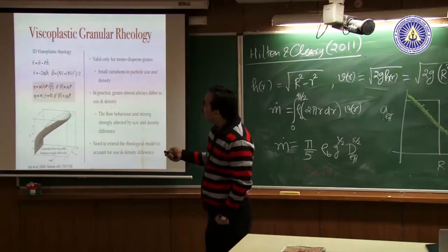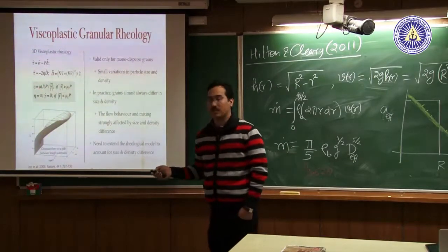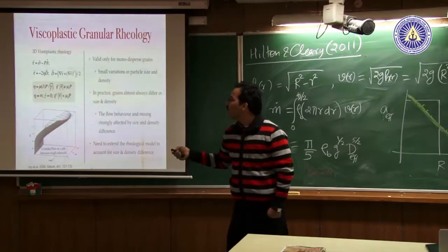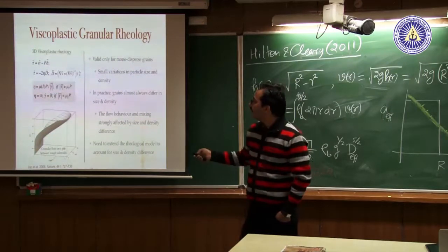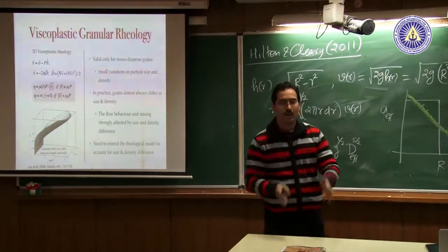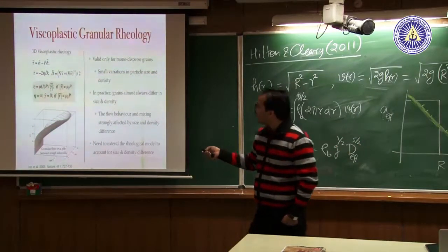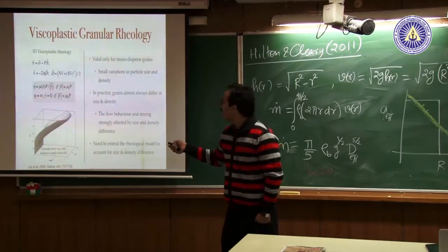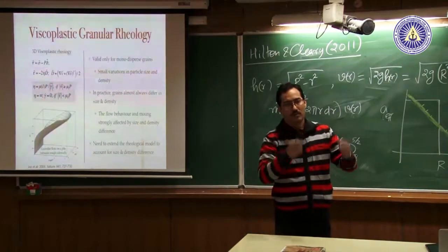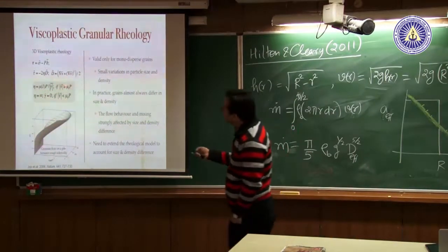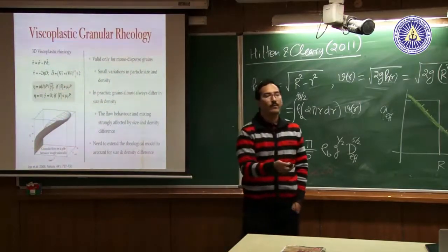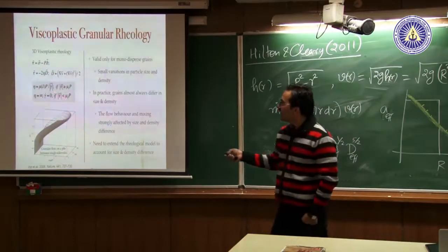The effective viscosity is some mu(I) times pressure divided by the magnitude, the second norm, of gamma dot, the shear rate tensor, and that is valid only when the second norm of the shear stress tensor is greater than the minimum that you require, mu_1 p. Otherwise your viscosity is infinity.